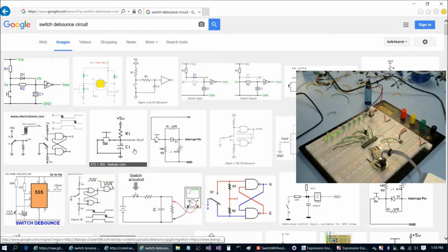So to put two NAND gates or a Schmitt trigger on your board, that means putting a whole other chip on your board. And that's inconvenient in pretty much any context. If it's in a prototyping or hobby context, that's going to be unfortunate, because what if you don't have one of those in your bin at the moment?